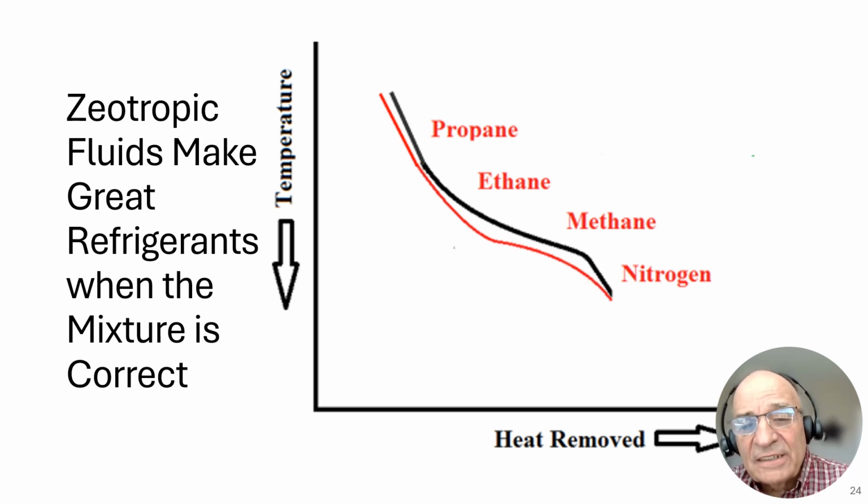But you have to watch out. You see this right here and right here? You have to watch out not to have what's called a pinch point, where this curve gets on the other side of the load curve. Your refrigeration gets on the other side of the load curve, your refrigeration process essentially stops because it's trying to go in reverse. Heat only transfers in one direction from hot to cold. So you got to watch out for pinch points, and that's all part of the design. And that would be your load and refrigeration curve as shown for the process that we just showed.